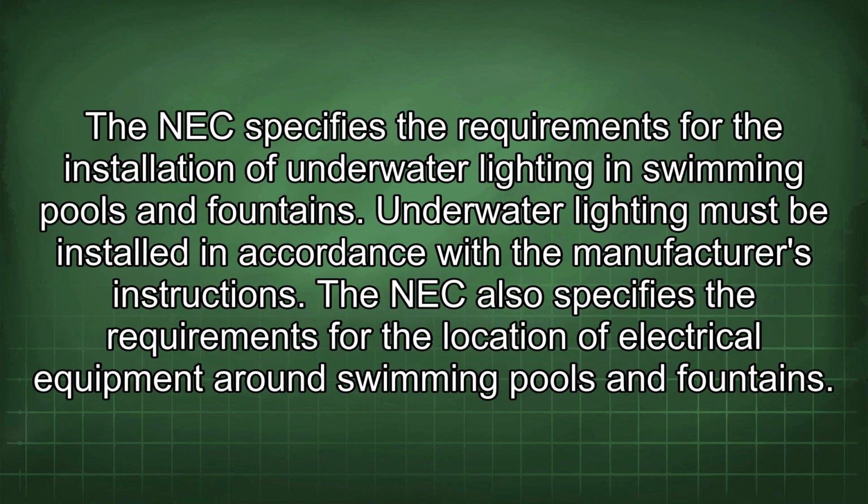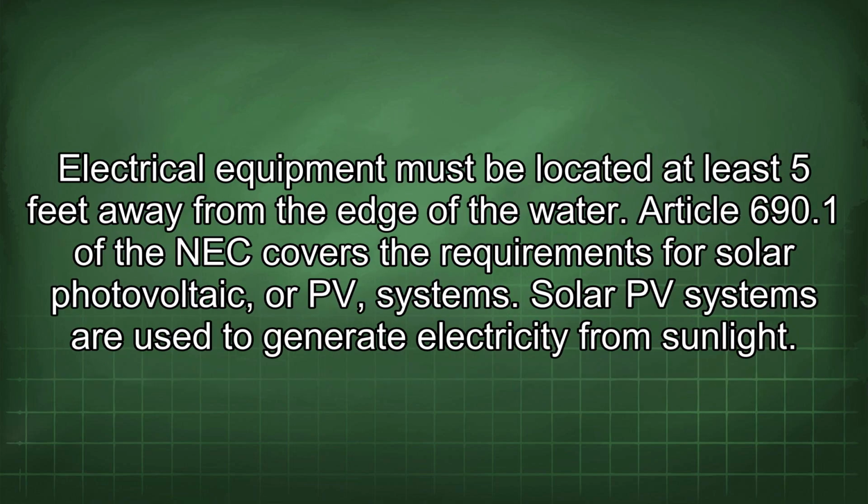The NEC specifies the requirements for the installation of underwater lighting in swimming pools and fountains. Underwater lighting must be installed in accordance with the manufacturer's instructions. The NEC also specifies the requirements for the location of electrical equipment around swimming pools and fountains. Electrical equipment must be located at least 5 feet away from the edge of the water.